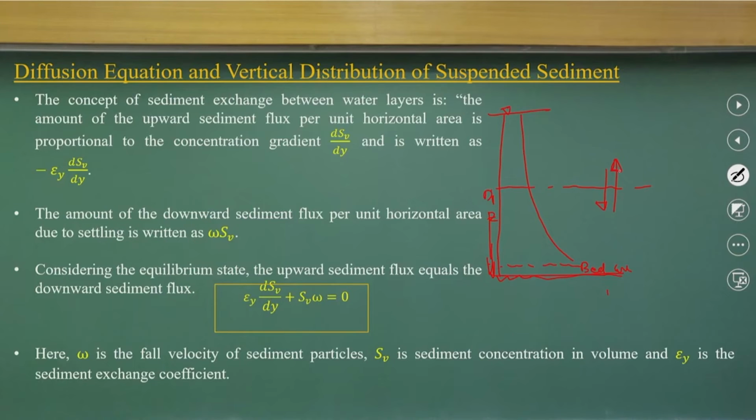The sediment flux going down and the lifting up should both be the same. Going down is very easy: you know the settling velocity, so with the sediment concentration C S B you can find out the amount of sediment that will fall down with a settling velocity.